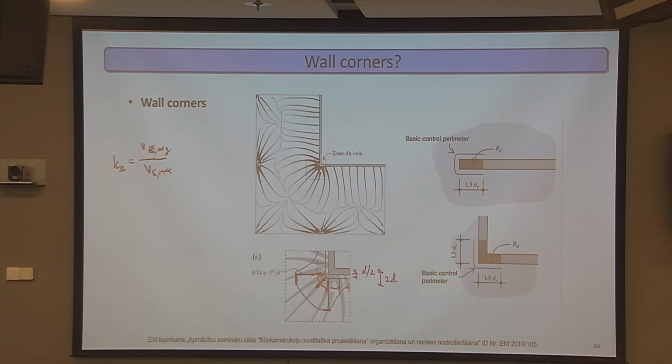Then if you actually do a nonlinear analysis of an end like this, the same way as I showed that it's enough to consider flexural nonlinearity to have more plastic distribution of shear forces, it also applies in the ends of the walls.